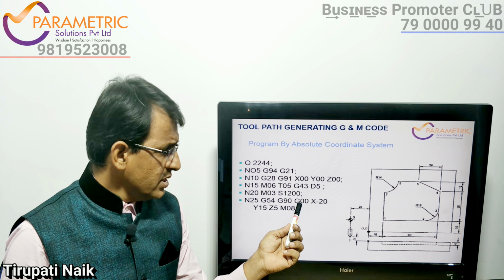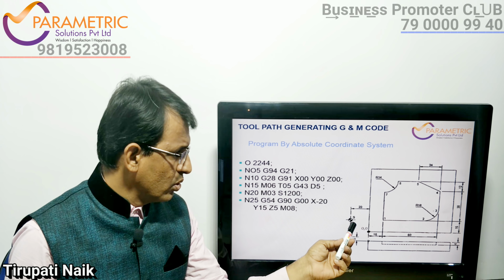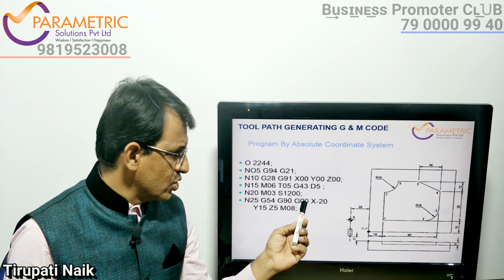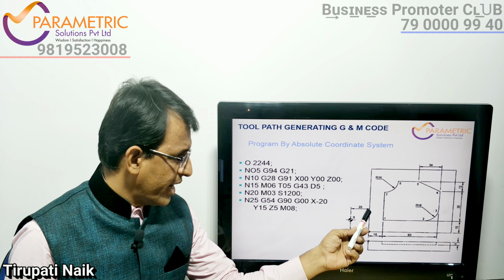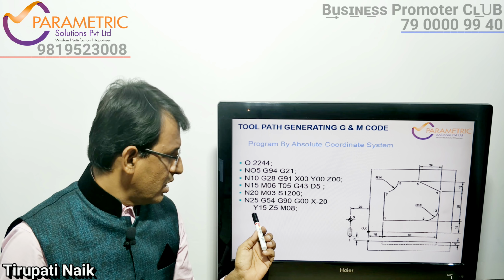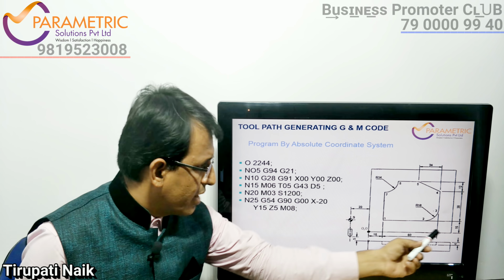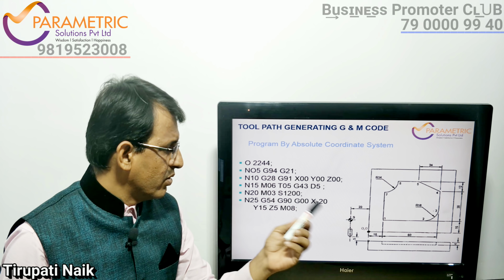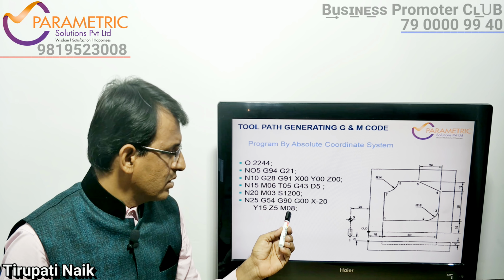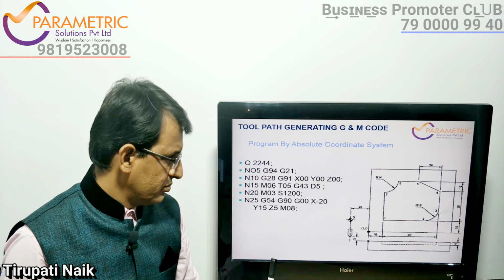Then this is the rapid traverse, where the tool moves from the home position to the start point, that is G0 X minus 20 from this origin, and Y is 15 mm distance from here, and Z axis is 5 mm above, and here I start the coolant with M08.